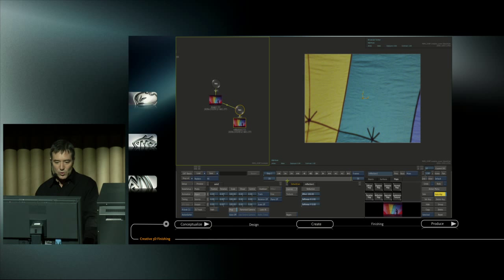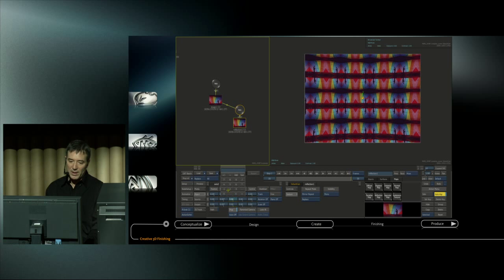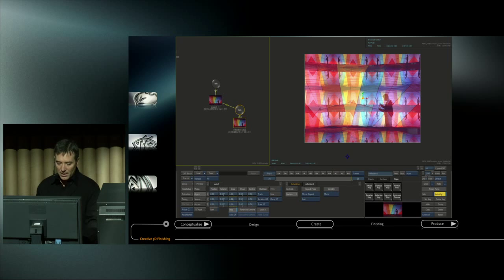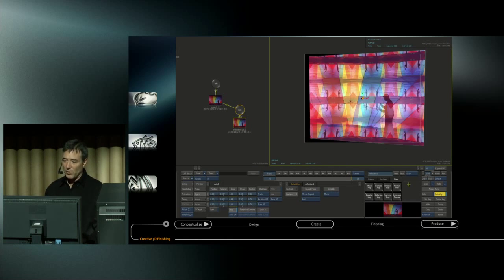But notice there's new controls for the reflection map. There's things like an effect and a softness parameter where we can do GPU-based softness. If we go into the texture menu, there's new options like mirror repeat. So if I bring the scaling down on the mirror repeat, let's bring that down to about this size. Now we're actually able to repeat that texture, and in the repeat mode field, we can change replace to additive, and now we're getting a proper reflection. So that's starting to look pretty cool.